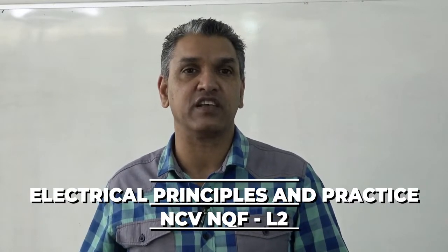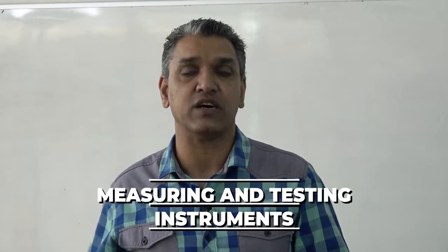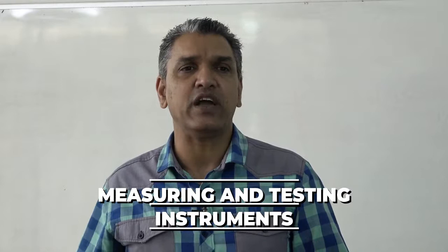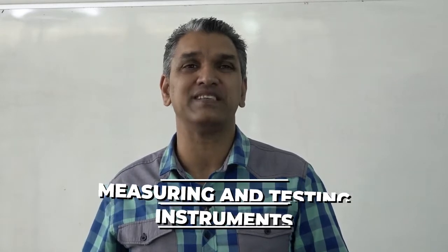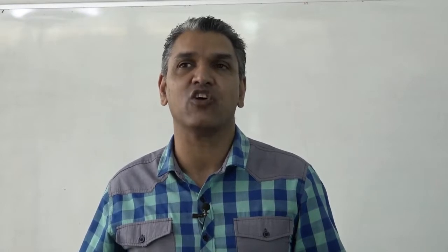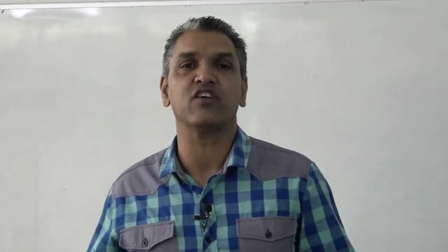Let's take note of a few things from the table that we have indicated on our slide. When we are using moving iron instruments, our measurement is done in AC and DC. However, with our moving coil instrument the measurement is only in DC. In moving iron instruments, our scale is nonlinear. In moving coil instruments, we use a linear scale. In moving iron instruments, they are controlled by spring or gravity, whereas moving coil instruments are controlled by springs.